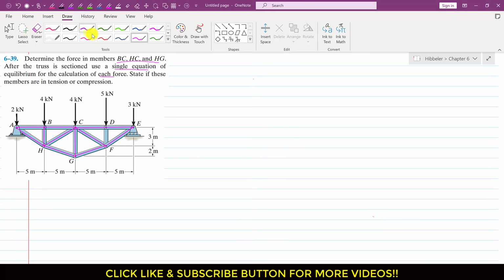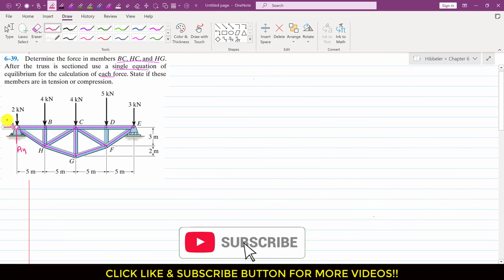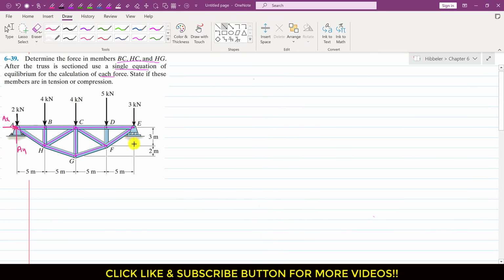Since at A we have a pin joint, we will have two reactions, right? So let's say that here at joint A we will have one reaction acting vertically upward, let's say this is AY, and then one reaction acting in this direction, let's say this is AX. And at point E, since here we have a roller support, we will have the reaction in this direction, let's say this is EY.